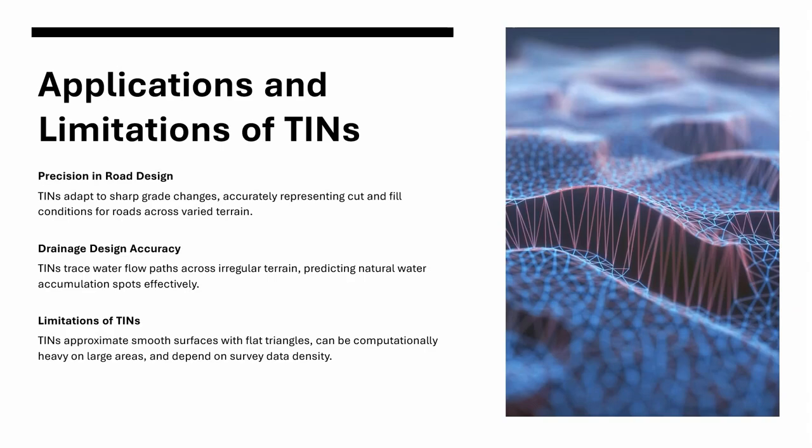And of course, no model is perfect. TINs do have limitations. Discontinuities in TINs assume that each triangle is a flat plane. If a hillside curves smoothly, the TIN approximates it with a series of facets. The result is a piecewise surface that may look jagged compared to reality.